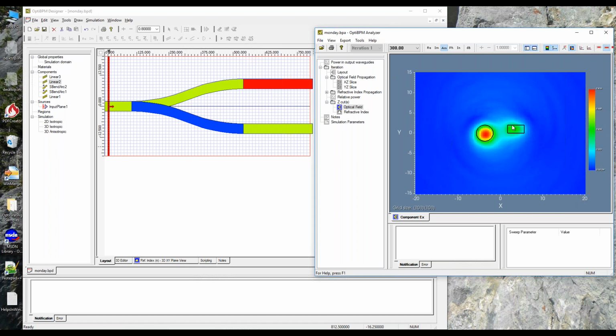With the two waveguides having split, 300 is about here somewhere. So there is the channel on the upper side, and there's the fiber on the lower side. And later on, at 750, by this time they were, again, both channels, but it looks like the lower one stole most of the power.